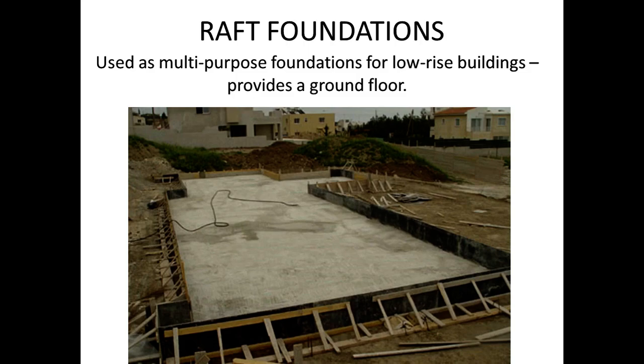For many buildings, you'll find a raft foundation, and a raft is a continuous, again, reinforced concrete floor that's poured onto the ground. The reasons for a raft are twofold. One is that, of course, you can now take load pretty much anywhere onto this. You don't have to just follow the line of the strip, do you? So if you wanted a column here, you want a bit of load-bearing wall here, or a kind of variation, it's an easy way of taking load back to ground.